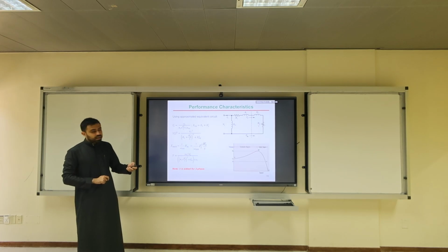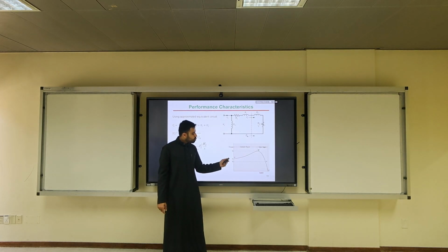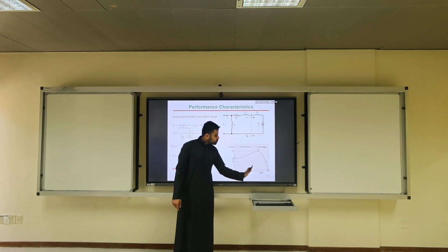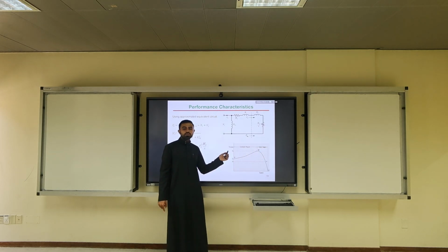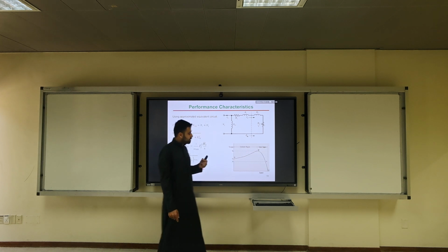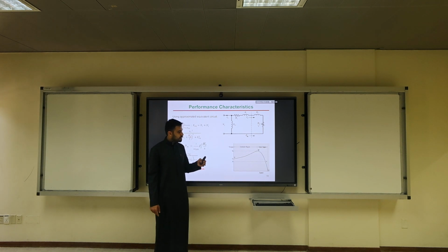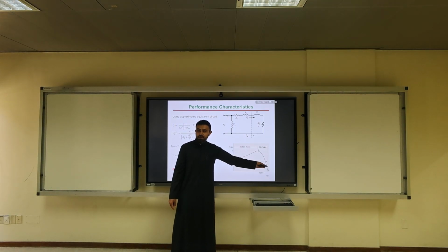The torque speed characteristics. In terms of stability, once you turn on your machine, you should really operate it in this linear region, where you have the stable region. Anything unstable, you're allowed to operate only during transients. So let's think a little bit about why this curve is important. First of all, is this curve always fixed, or does it vary for every machine?